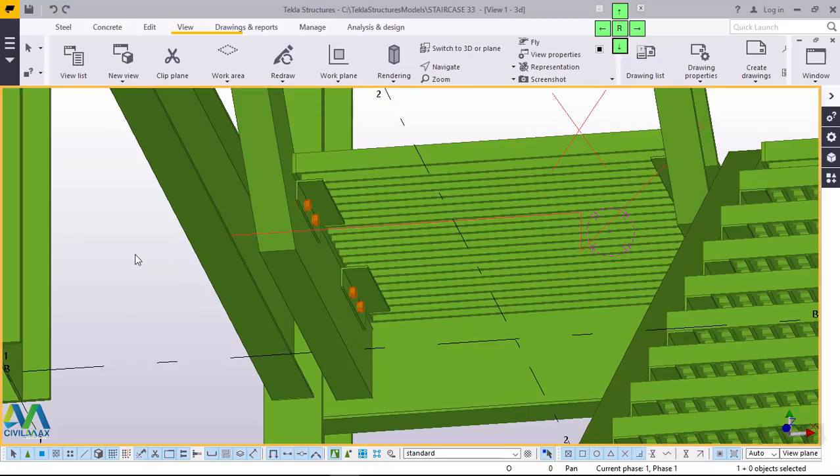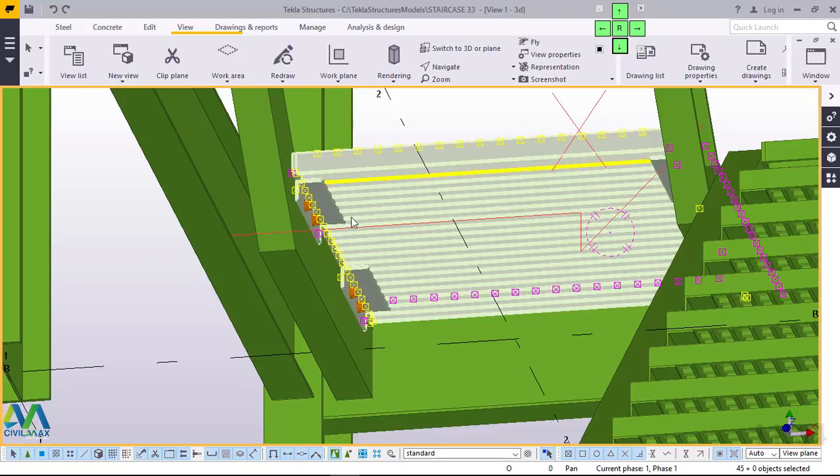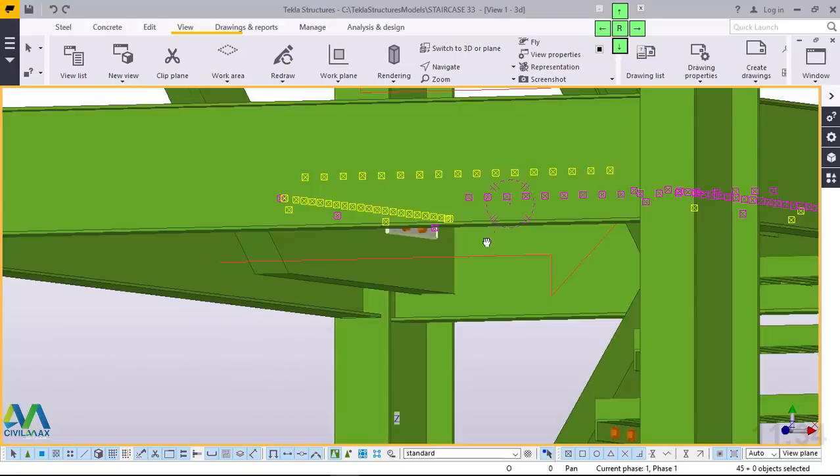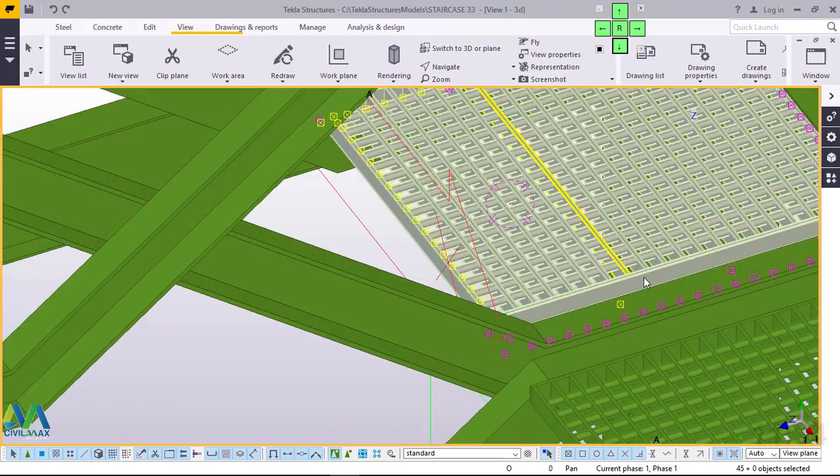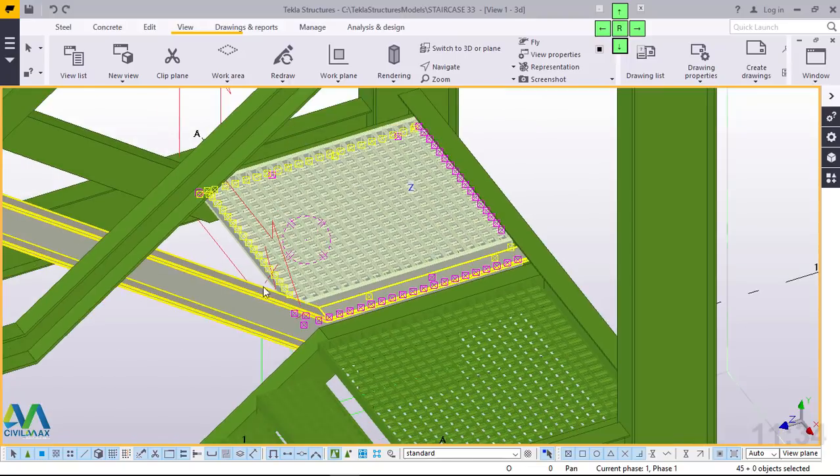Perfect. Then click on Empty Screen. Then when you come back to Alt and confirm that everything will be selected under one assembly, then we'll want to offset this slightly down at a distance of 50 millimeter.